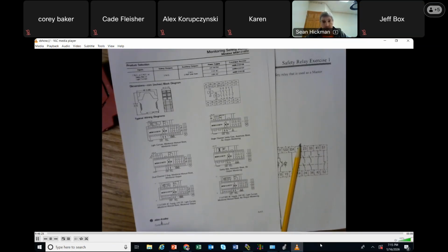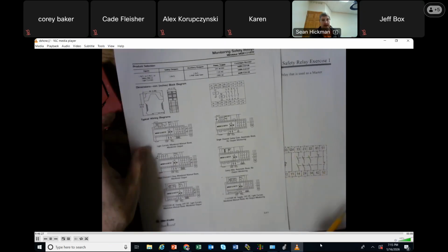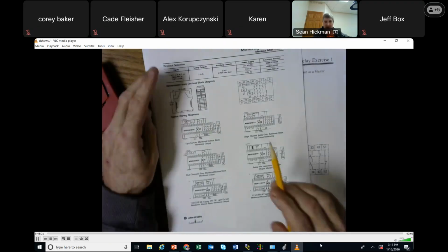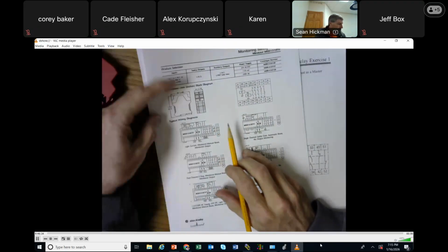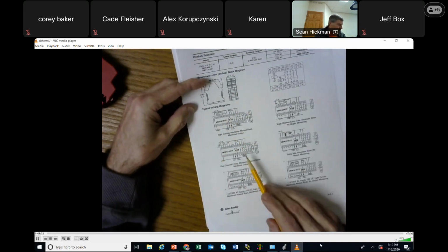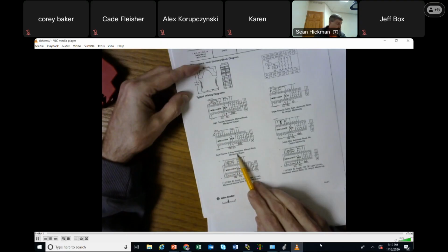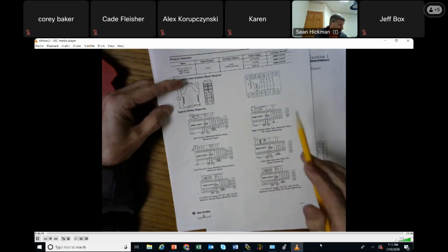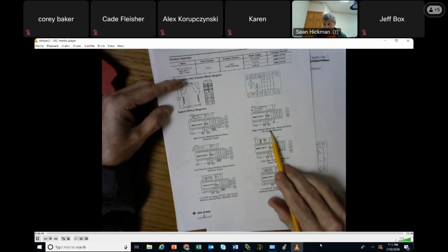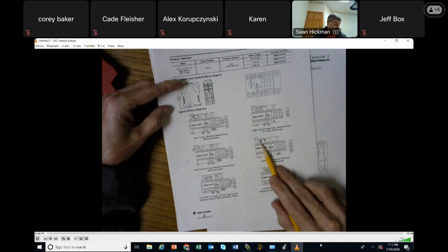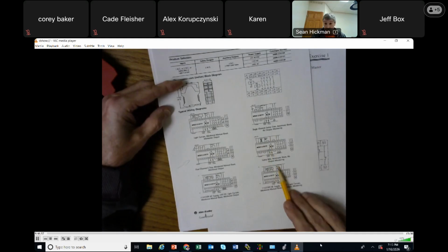Okay, so I'm looking at the wiring diagram for the MSRP right here, and some of these tell you what we're looking at. Here is one for light curtain, so we're not using that. Here's one for dual channel e-stop. This is a nice one here that we're going to use. Here's a light curtain again. They're big on light curtains. Here's a single channel safety gate, and that's the latching for the gate. It shows you how to hook up the gate. Here's a safety mat. These are some of the different ones that are coming in here.